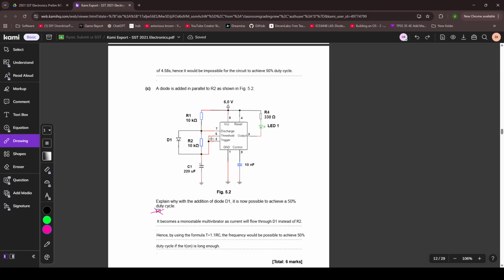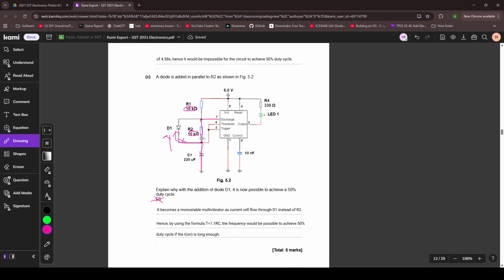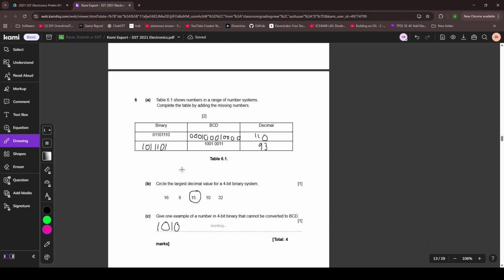And then when discharging, the current will flow through this resistor and then discharge. And it cannot go up here to go through this. Why? Because the diode prevents backflow of current. So when discharging, current flows through one resistor only. And in charging and in discharging, the resistance of the resistor is the same, 10 kilo ohms, 10 kilo ohms. And that's the reason. Okay? Alright.